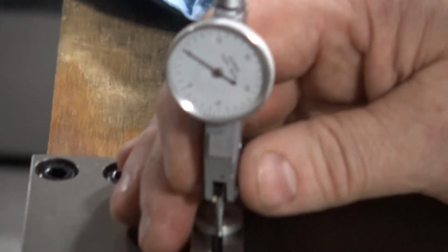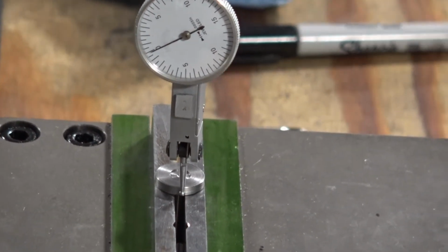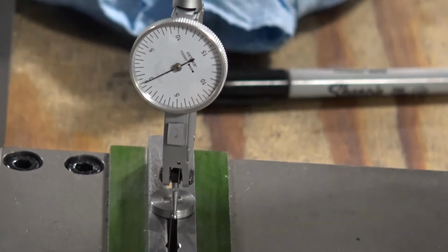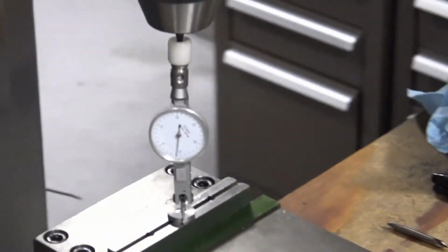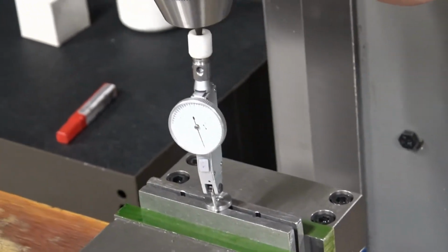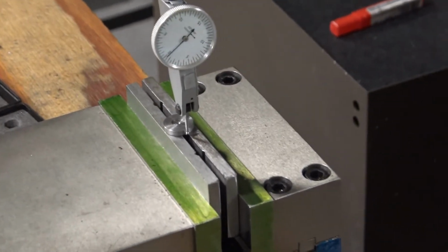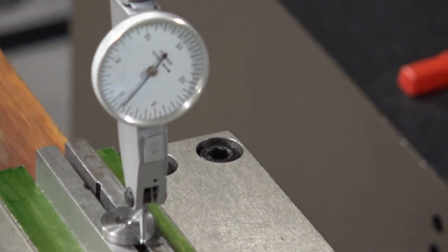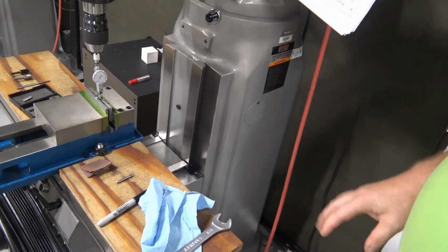This is all part of the steps that you have to run through to get this thing indicated in. Okay? So now I've got 15 thousandths worth of preload again. I'm going to rotate the spindle 180 degrees. Notice that it's rotating counterclockwise, and now it's coming back. Now why is it coming back? Well, it's coming back because the front to back is actually out. So it's reading more of an elliptical shape.